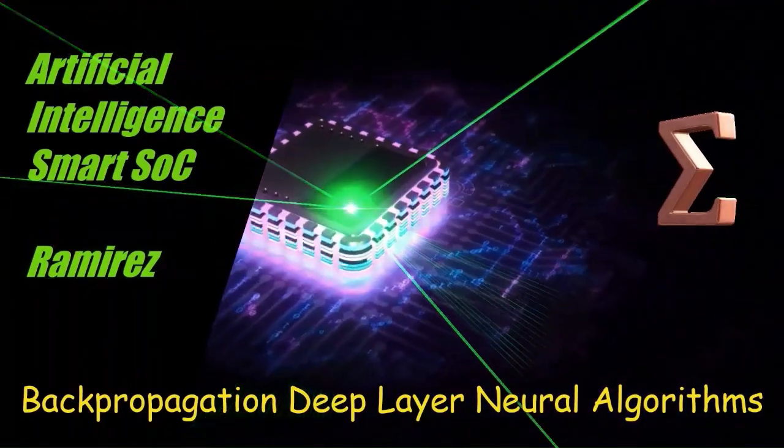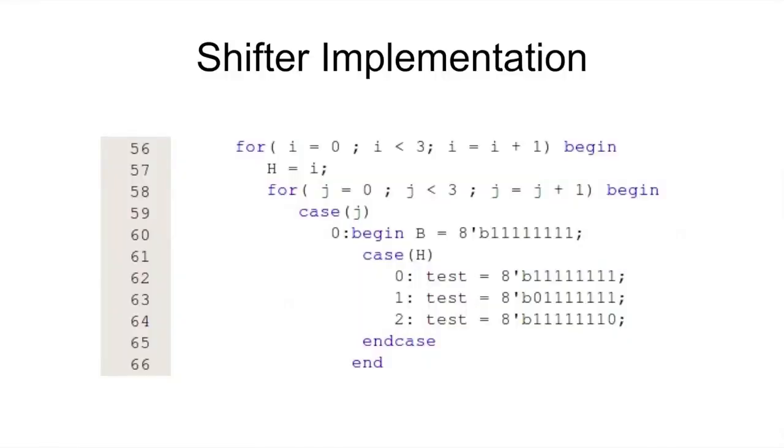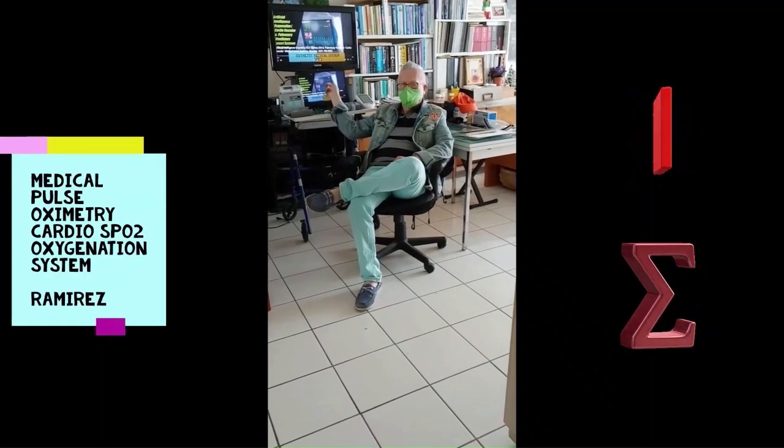This methodology allows tight clock skew and timing objectives to be met. It also allows timing problems requiring logic or placement changes to be identified quickly before running a relatively long routing iteration on the majority of the nets.